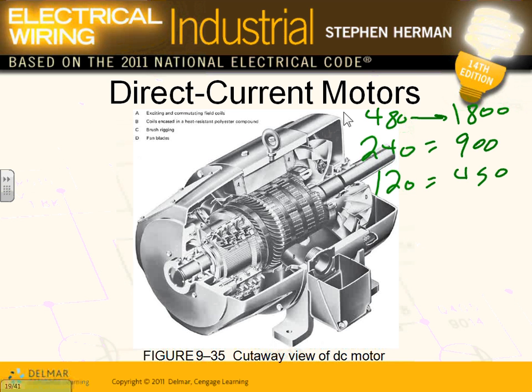Their problem, though, is their high maintenance. A lot of maintenance has to be done on the brushes. They have a lot of brushes, guys. Imagine having a brush tied to a rotating object, like a fan rotating, and there's a brush tied to it all the time. What's going to happen over time when things are rubbing against each other day in, day out, for hours? They're going to malfunction. So a lot of maintenance is involved in maintaining that system. That's really the disadvantage of them, very high maintenance. You have to change the brushes. You have to go clean the stuff over here, so the high maintenance, big deal.